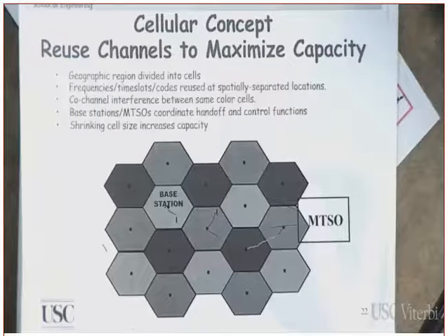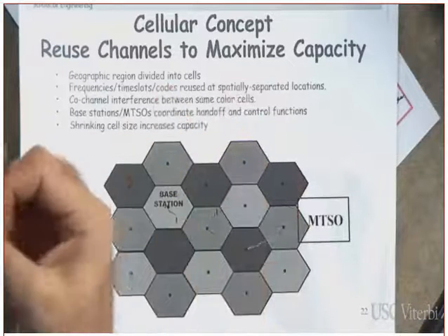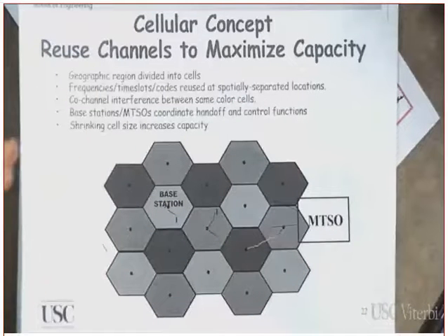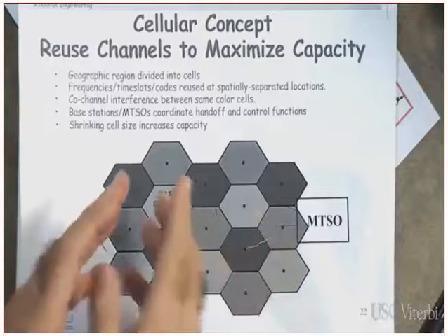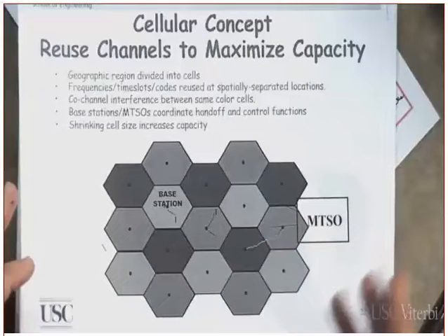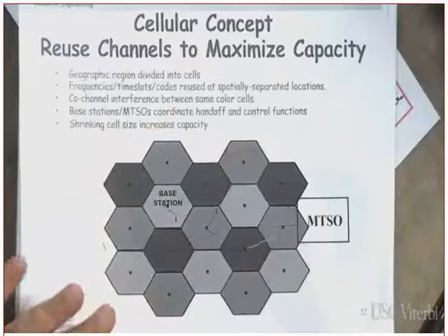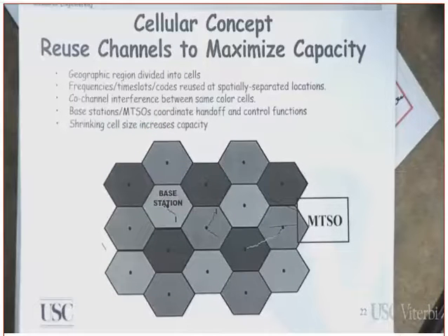The question here is that there is no empirical formula that I can just plug in. It's all based on what? Measurement. And companies like Qualcomm, they take their truck and they measure what? They measure the power, the received signal strength, RSSI. They call it RSSI. They measure it in what? In multiple locations within the area, and they come up with a mathematical model to cover how much the signal is losing. Clear? So if they are separated, the longer the distance is, it means what? The signal will lose its what? Its strength, which means the interference will become lower. Clear?